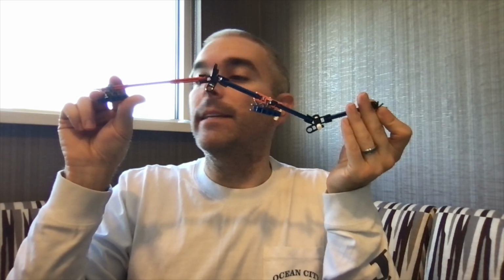which is this fixed end over here. And so what we're going to do is shift this up one, right? But I have to hold this in place, so something like that. So I'm going to shift this up one. And so what does the displaced state look like? See, this goes up one. Because this is a fixed end, it can't really move. And so it has to stay at one, straight all the way across there. Then it starts dropping down. It passes through zero at this support, drops down, and then comes back up. And then we can plot the values based off of that.